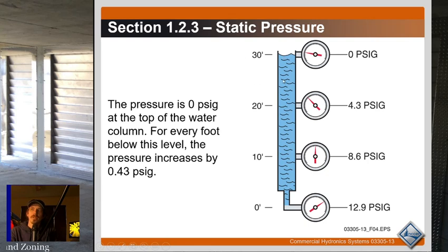If our boiler was on the top floor, we would only need 1 or 2 psi, right? Because at the bottom it's going to be 12 psi, but at the boiler itself, the pressure we should be reading is just enough that it's completely filled. Maybe 5 psi. You just have to make sure there's enough pressure in the system that you've got a full column of water to fill the entire system. In most cases, that's the maximum pressure you need. So 12 psi is a good starting point for most residential and light commercial boiler systems.